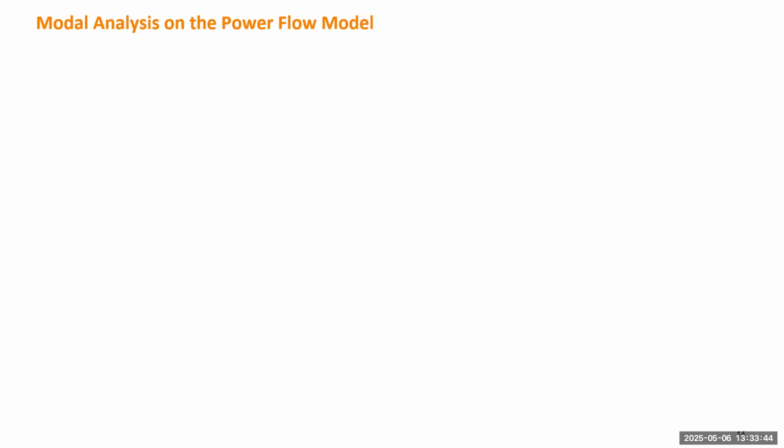Any question? Okay, so from these slides, we're going to generalize the measures based on PV curve and the VQ curve to a bigger system. We talk about the modal analysis. So modal analysis has been introduced in the small signal stability section when we studied the oscillation damping for the dynamic of generator. But here we can use a similar measure, but this modal analysis will be conducted on the power flow model, not the dynamic model.